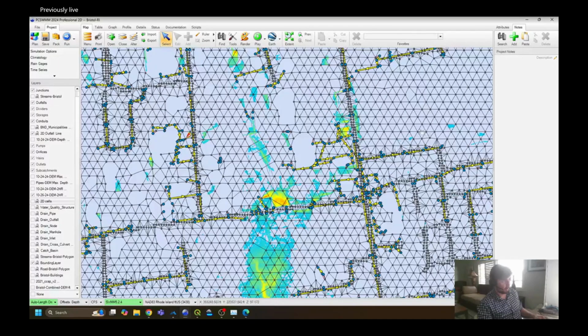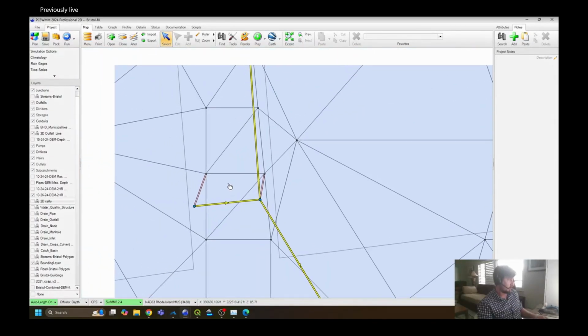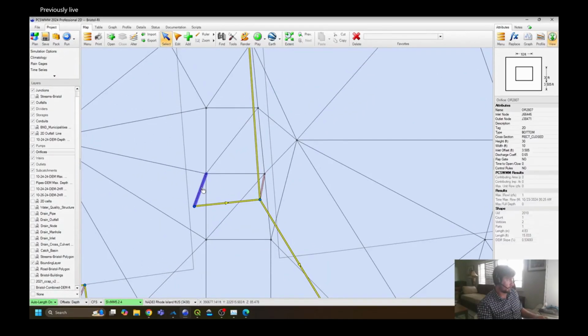There was a question I can demo here about inflows and outflows from catch basins. In this case, I'm using an orifice connection here, a pretty wide orifice connection. I can change this to be whatever type of inflow outflow I want, whatever rating curve I want. But to answer the question, it is a two-way street. Water can come in and it can come out. Let's see if I'm getting all the questions.